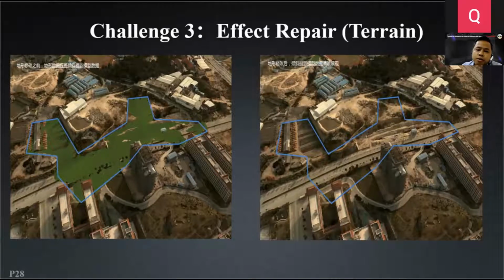But we don't want to modify the original data. We can use one of the SuperMap iDesktop functionalities, which can modify terrain data at display level without actually modifying the original data. As the picture shows, on the left side, before the terrain is modified, the terrain data covers the oblique photography model. After the terrain is modified, the oblique photography level data is clearly displayed.